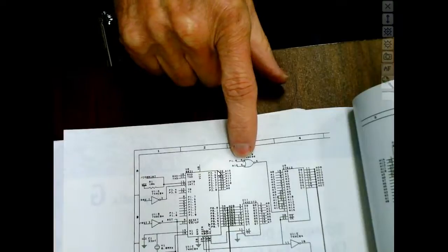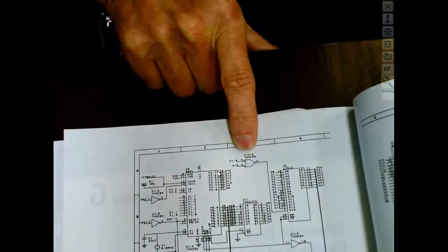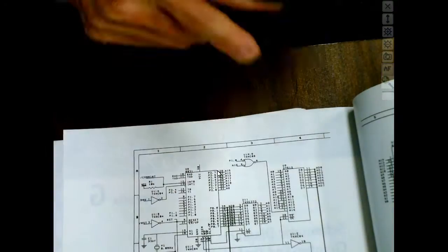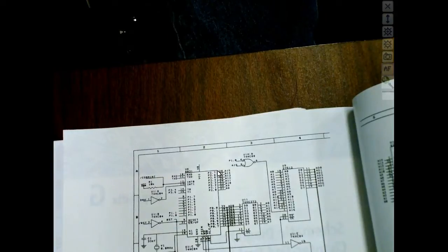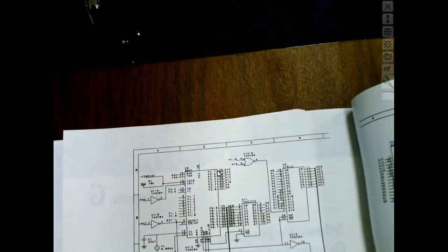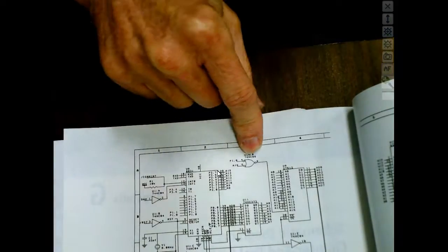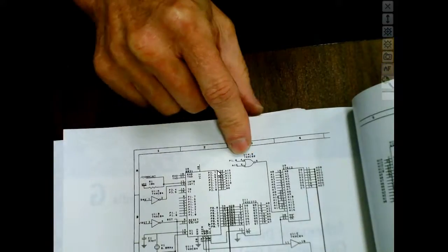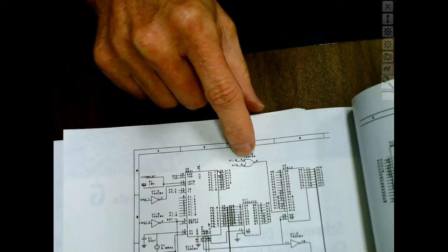Now this is an AND gate. If I went out and bought this thing, I would buy an AND gate. We know what a 74HC08 is, that's a quad 2-input AND gate. But it's not drawn as an AND gate, right? You understand? The 7408 is an AND gate, and this is one of the first guys we're going to use.